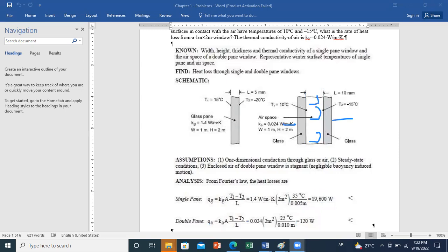Inside. Okay, inside. Look, a very small gap will restrain fluid motion. If you put air in a very narrow gap, it will not have the freedom to move. And because you have velocities very close to zero, convection is nearly zero. Convection will be enhanced if you have fluid motion, and fluid motion will start when you have a relatively big thickness, because this will give possibility of currents of air, and this will lead to convective fluxes. How do we know the range of the thickness?